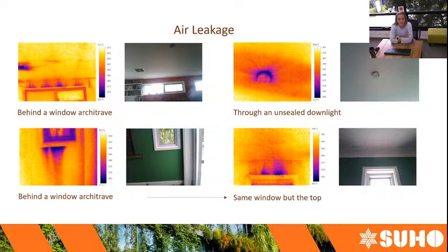So you can see there that there is a lot of leakage coming from the top of that window, and generally what happens, I'm finding, and I'm hearing reports from a lot of people in the industry as well over time, is that builders, because they're usually restricted heavily on time and budget, cut corners when they think nobody will notice. So up that high, that window is near the ceiling, they potentially would think nobody is going to ever look there to see if there's been silicone applied or if it's been painted, and they leave it. So these are the kinds of little defects that thermal imaging and air tightness testing pick up really easily.